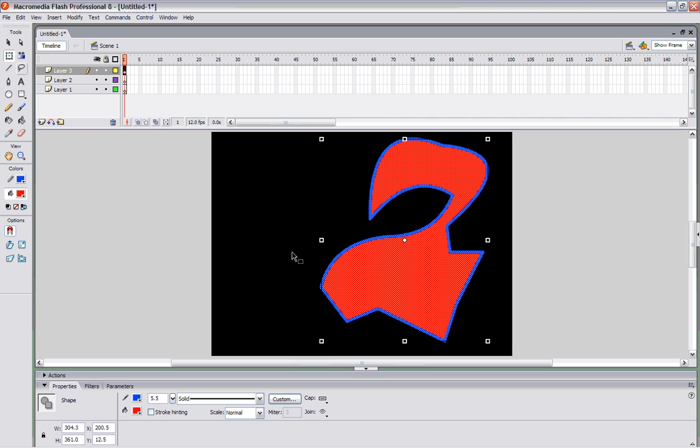Let's talk about what free transform can do. This is our pivot point, and this is important for you to know what that is, and we'll talk about that in a little bit. But with free transform, I can scale this both horizontally and vertically. If I hold the shift key down, I can do it so that it's at the same ratio both vertically and horizontally.